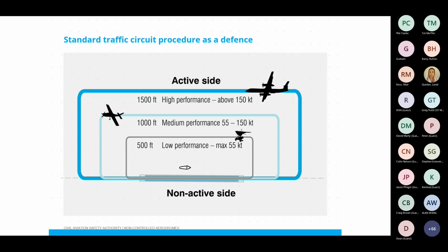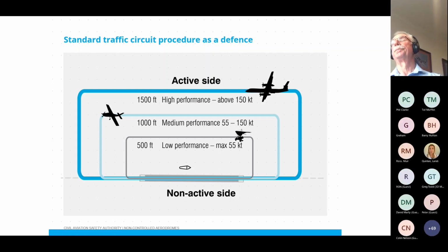And this helps to segregate the traffic as you progress downwind. But of course, the issue is that eventually you need to turn base and final approach, and this is generally where the problems might actually be occurring, when you lose that general segregation of traffic as you're coming around base. So Neil, I might ask you, do you find that pilots don't project ahead enough, to assess conflicts around base leg and onto final approach, given that they're vertically segregated as they're going downwind?